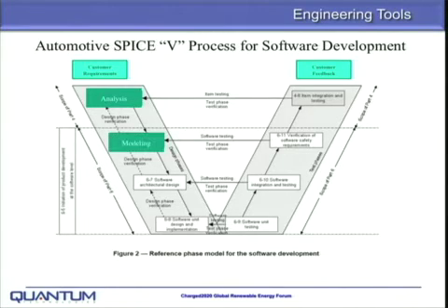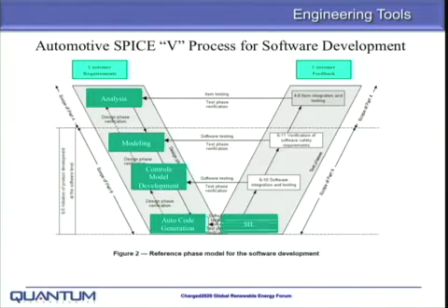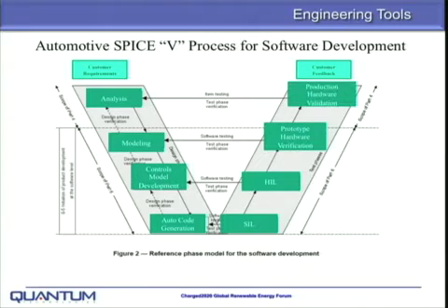And then as you come down the V over here, you do modeling, controls, model development, go through the auto code generation, come back up the other side here, where now you're doing software in the loop, hardware in the loop testing, which is really bench top testing, and then get into prototype vehicles and hardware vehicles. So I mentioned this real quickly. I'll actually use this a little bit later.